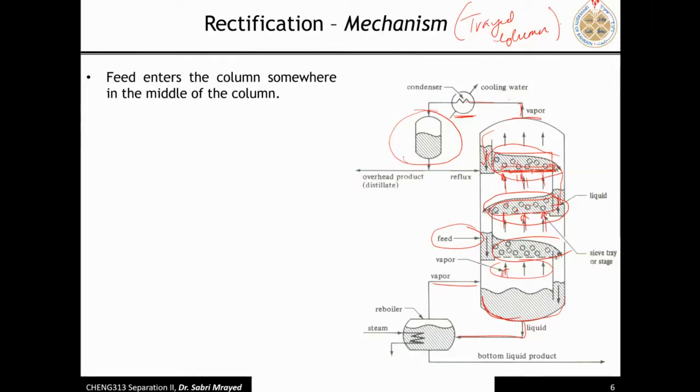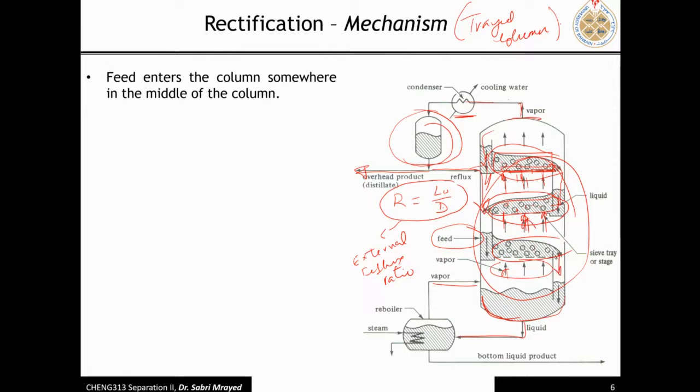And then once you have the liquid formed here, you take part of that and put it back into the column, so you keep the mass transfer taking place, and part of that is going to be going down. So this reflux ratio is called L0 over D. This is called the external reflux ratio. For each stage, for example, the L over V, the quantity of L going down to the V going up, is called internal reflux. We'll explain that when we develop the equations.